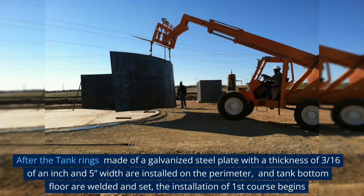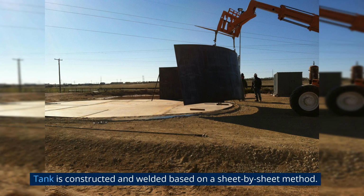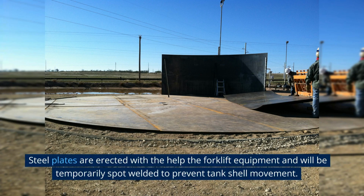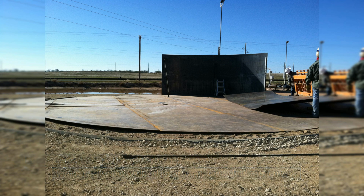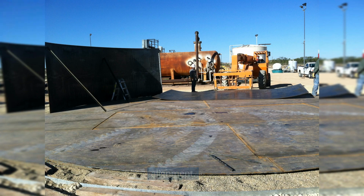After the tank rings made of a galvanized steel plate with a thickness of 3/16 of an inch and 5 inches width are installed on the perimeter, and tank bottom floor are welded and set, the installation of the first course begins. Tank is constructed and welded based on a sheet-by-sheet method. Steel plates are erected with the help of forklift equipment and will be temporarily spot welded to prevent tank shell movement. Welders will continuously check the center measurements and vertical alignment.